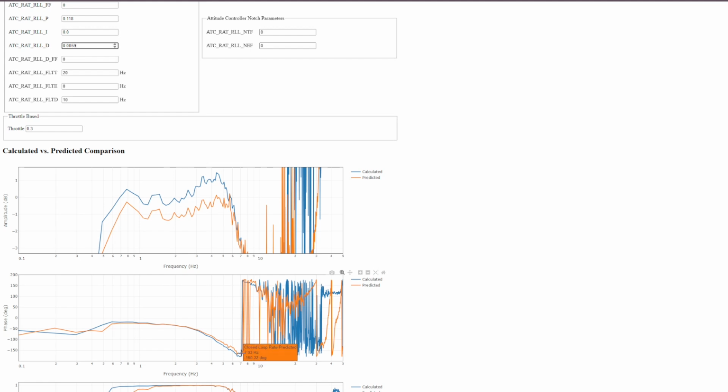And so my rule of thumb there is that at the 180 degree point, where you can see it flicks low to high, I don't want that to be greater than 3 dB above the command. Sorry, I want it to be half, so minus 3 dB relative to my command.